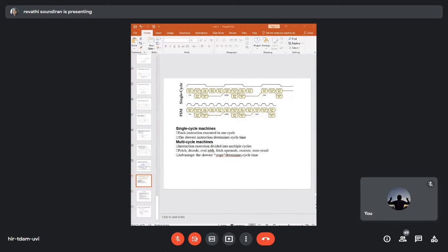So now this is comparing the high level idea of your FSM processor with your single cycle machines. As we already have, the basic operations are fetch instruction, decode instruction, read registers, register arithmetic, then the read memory operation, write memory operation, write registers, and update the program counter. These are the basic fundamental stages of an instruction. But it differs with the type of instruction that you're using.